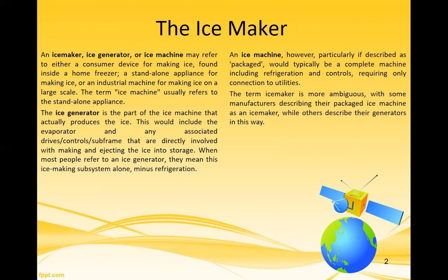The ice generator is the part of the ice machine that actually produces the ice. This would include the evaporator and any associated drives, controls, and subframe that are directly involved with making and ejecting the ice into storage. When most people refer to an ice generator, they mean this ice-making subsystem alone, minus refrigeration. Diba? So an ice machine, however,